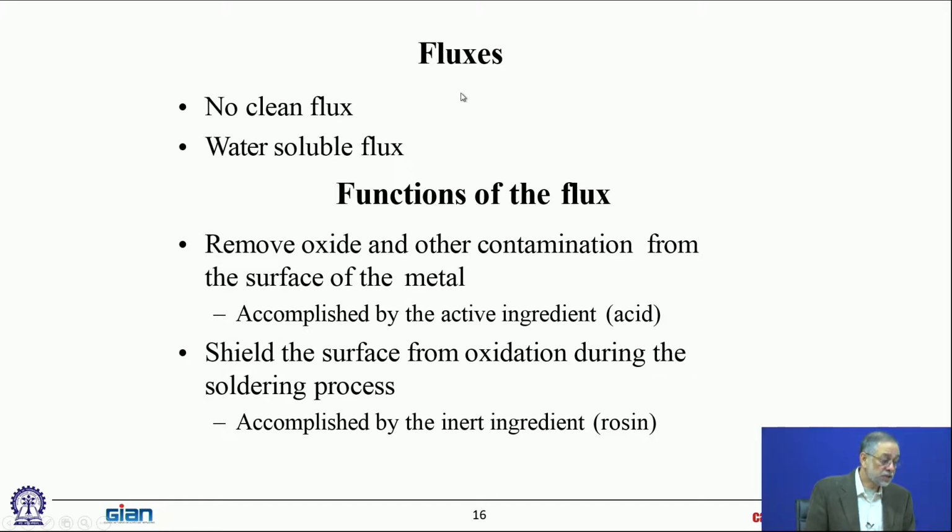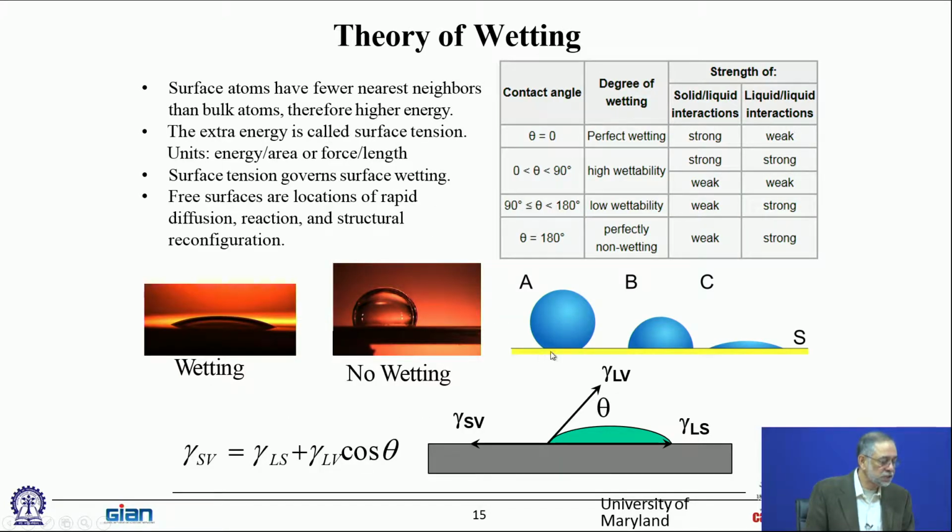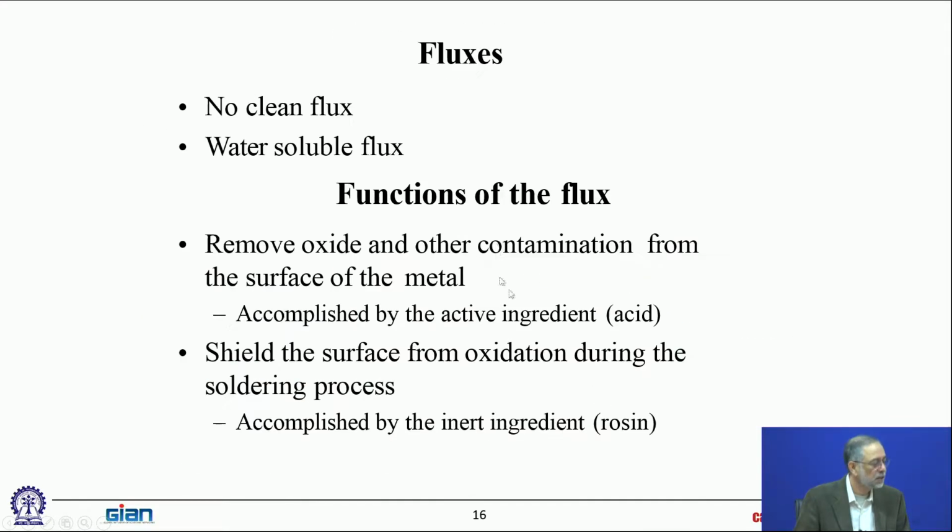Okay, then fluxes. So the solder material has to have fluxes because the moment you raise the temperature to melt it, at high temperature, the materials will oxidize instantaneously. So you have to have some chemical reducing agent right in there to strip that, to not allow that oxidation, and remove any prior oxidation that had occurred in storage. So both of those sources of oxidation are a problem. So fluxes are used for that. Variety of different fluxes.